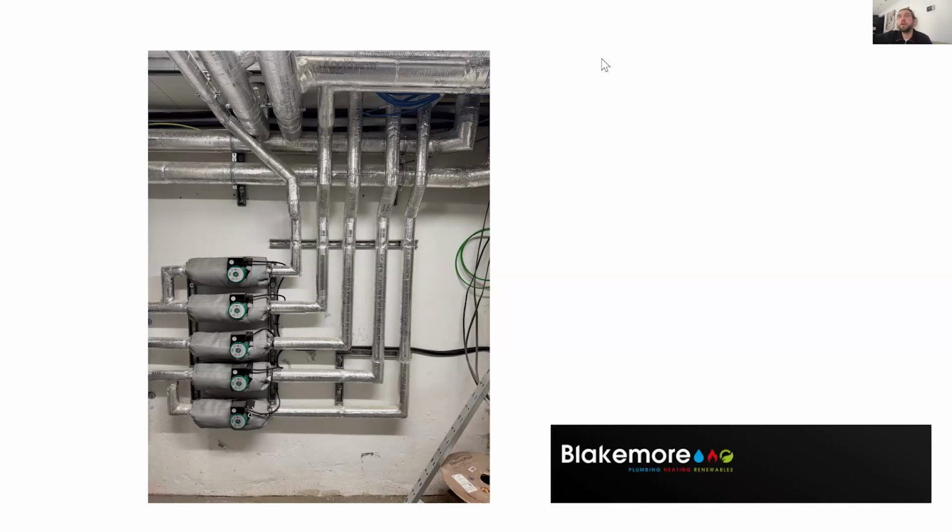The only thing I came across while doing it is whether it would be more beneficial to use weather compensation and a fixed blender on the secondary side from the buffer for the house. In times of high charge, when it's 65, I'm not going to be able to lower that temperature to below 45. It's going to be fixed. Whereas if I had a secondary, which I didn't think about until after the job, I wouldn't need to run weather comp in times of low tariff.